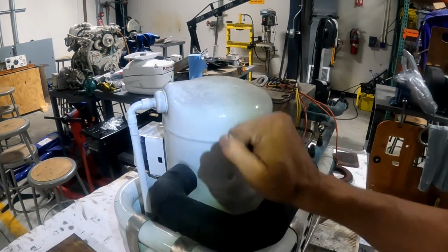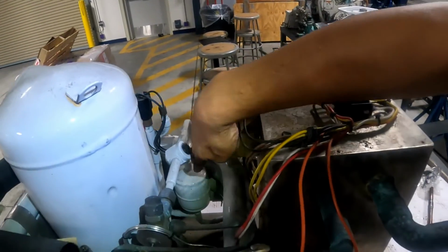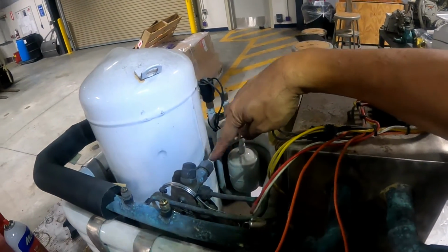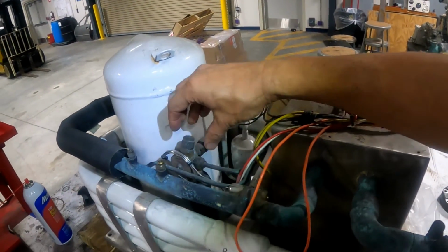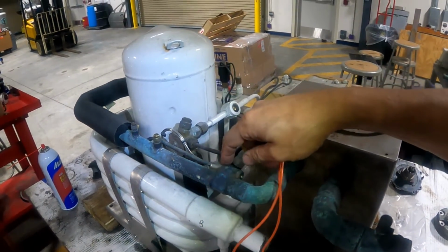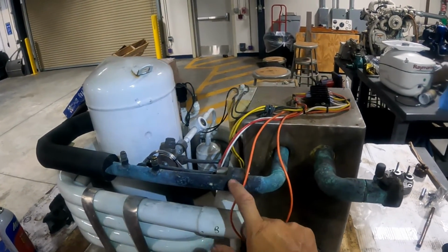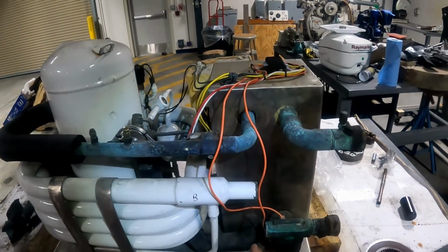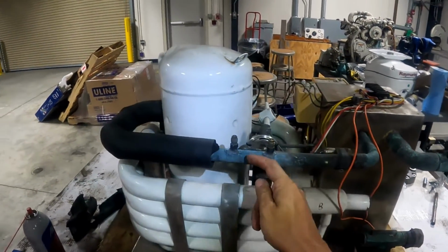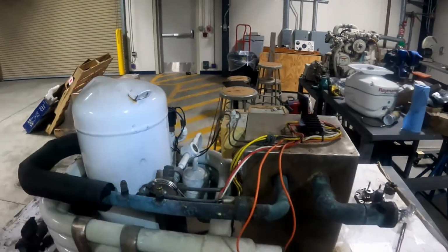The compressor compresses the refrigerant and sends it out with high pressure. The refrigerant passes through the accumulator. The refrigerant right now is liquid with high pressure and high temperature and passes through the expansion valve. The expansion valve opens and closes depending on the signal. The signal is coming from this valve, and this valve is touching this pipe with refrigerant internally. Okay, the refrigerant internally is coming from this serpentine. It evaporates, and the refrigerant right now is evaporated, and it enters again into the compressor. This is the cycle we are going to repeat.